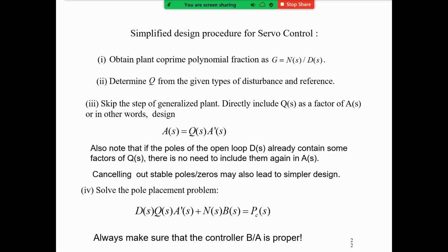There is only one exception. You can use an improper controller. That is the PID controller. If you say the final solution is a PID controller, I will allow that as the correct solution, because the PID in its simplest form is improper, because the derivative term is not a proper transfer function.